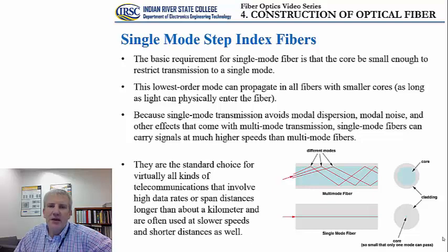So in this case, modal dispersion is completely removed since we have just a single mode, and since single mode transmission avoids modal dispersion, modal noise, and other effects that come with multimode transmission will not be present in this type of structure. And an immediate effect is that these types of fibers can carry signals at much higher speeds than multimode fibers.